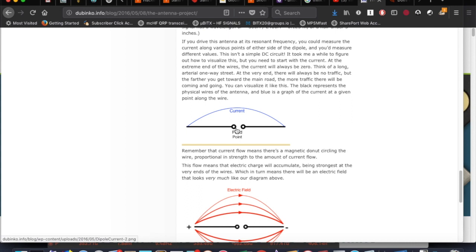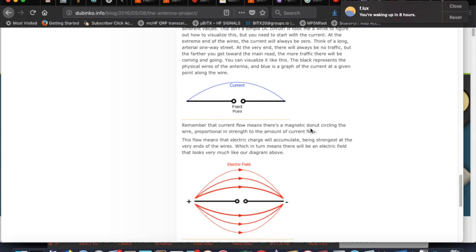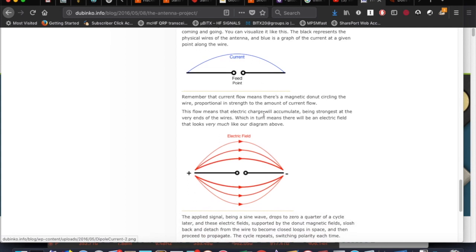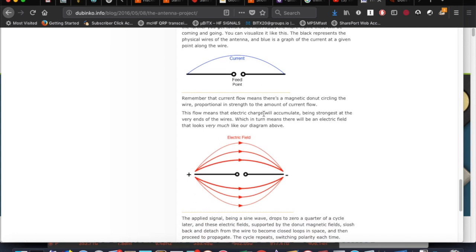Right? So speed of light, every AC frequency has a particular wavelength. You can make an antenna that matches that wavelength. And in fact, for it to be an efficient antenna, it has to be matched. The current at different points along the antenna here actually drops. It's highest at the feed point, and the current drops down to 0 at the very end. So this completely violates the rule we just talked about for AC or DC, where the current is the same throughout the circuit. Now we have different currents because there's energy flying around in radio waves.